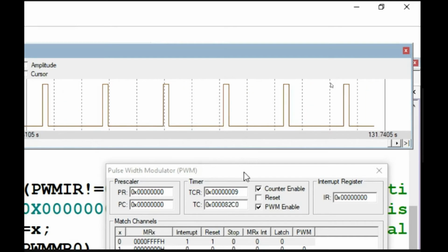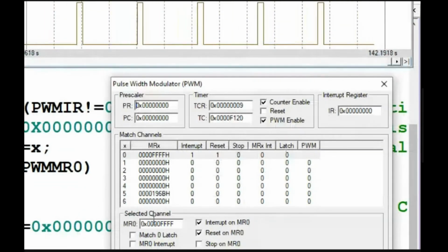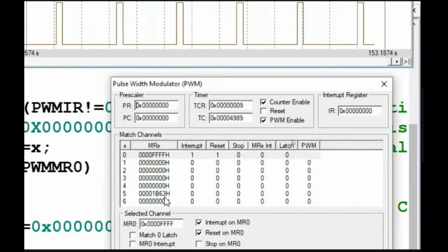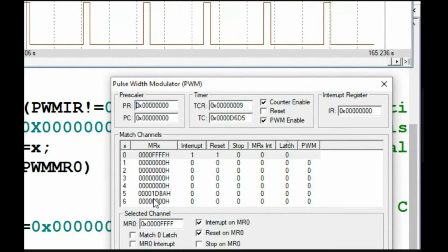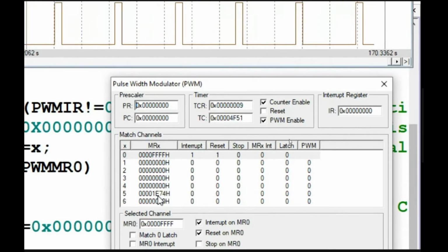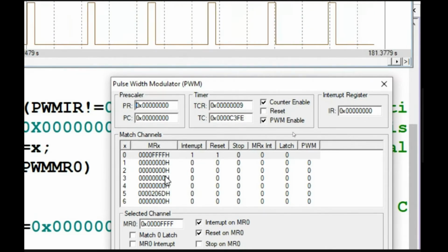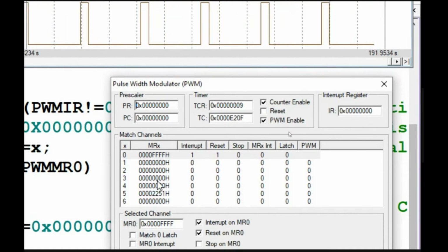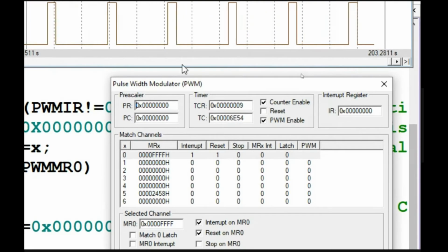See, every time you look at the PWM register, you see 1, 9, 1A, 1B, 1C; it is trying to reach the maximum. It is just 1 only, so it has to become 2, 3, 4. The period register value is fixed, and due to the cycle register values keep on increasing, the width keeps on increasing. Now it is only 2, so it has to come up to FF.